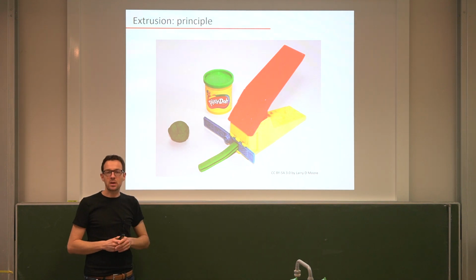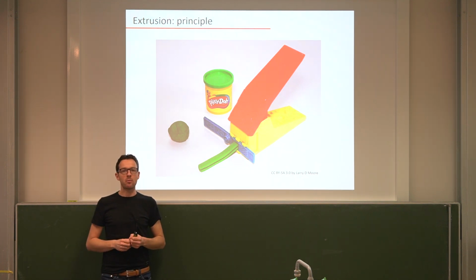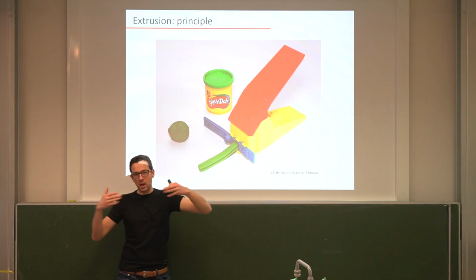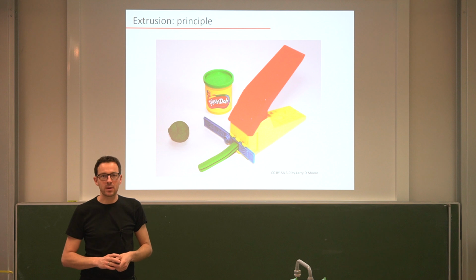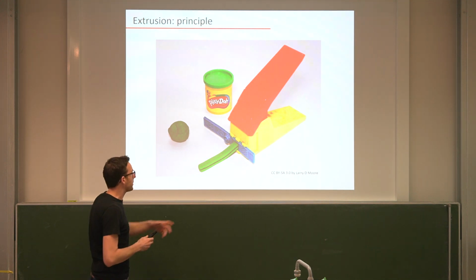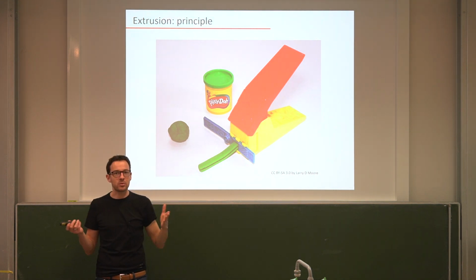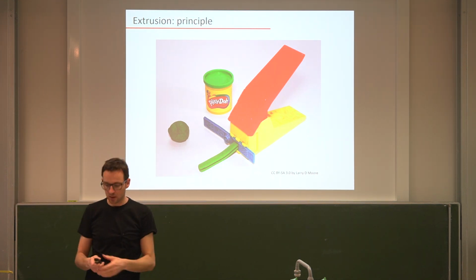So this is exactly how all these big polymer products are made as well, only that you try to avoid manual pushing, and of course use a bit of a more sophisticated upstream processing, but the principle here is exactly the same. It comes out through the die shapes the form, and then it comes out as an infinitely long string.